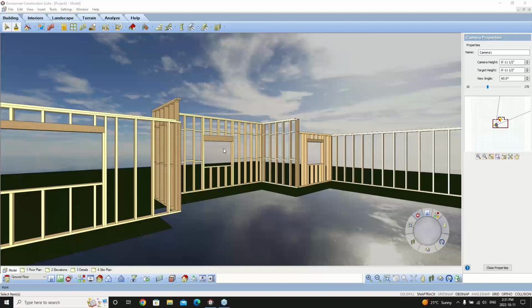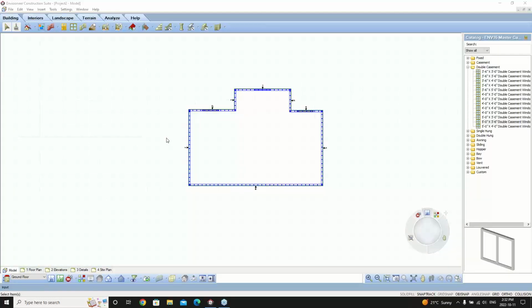So what you can do there is you can have a location. Let me see if I'm understanding this. So the 32-inch concrete block is going to have a wood floor, I'm assuming, and then the back half of the home, the back 2 rooms, are going to be on a slab. So you can do that by going in, and you can set up your own foundation levels if you want to. So you would be able to, and I'm just going to turn this off, so we're back into display all but framing.